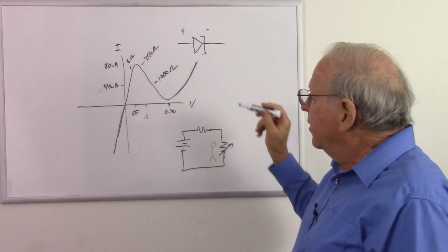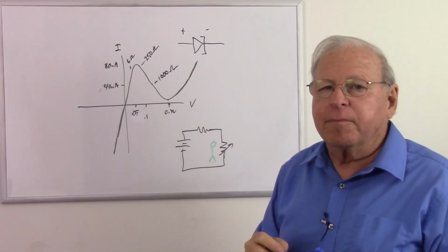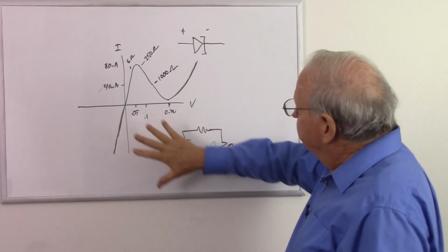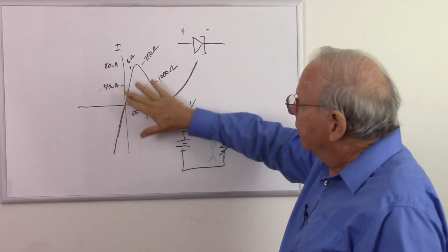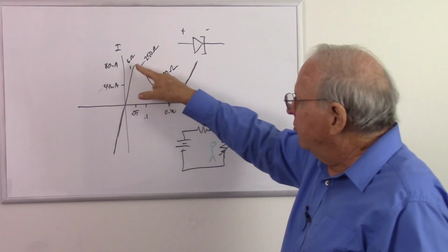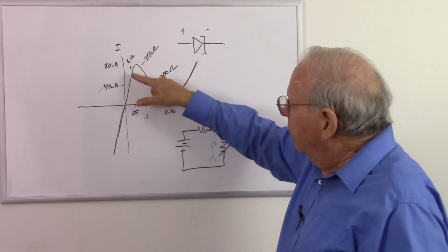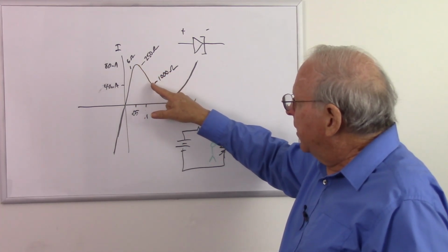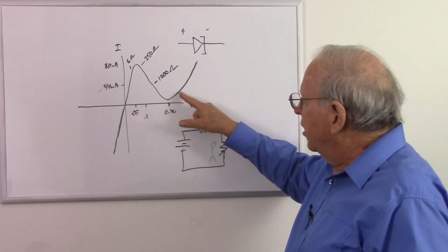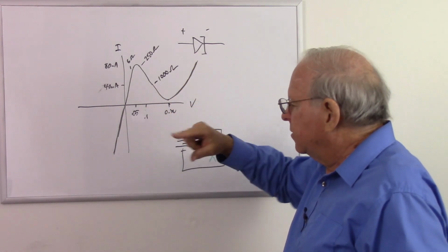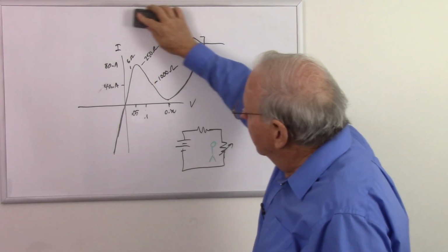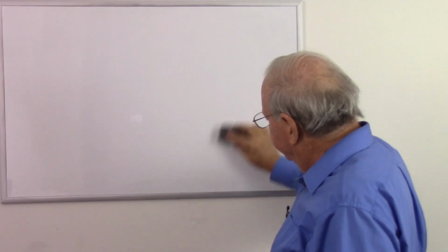So there is the basic idea of the tunnel diode. I do have a more thorough video on it, which you should watch if you're not following this. But that's just what it does. It follows that curve because the little green man makes it follow that curve. And it's just a change in impedance, about 6 ohms, about 250 ohms, about 1,000 ohms, just increasing its resistance exponentially. And then here it changes the resistance to follow a typical diode curve. Now we are ready to look at a tunnel diode relaxation oscillator.